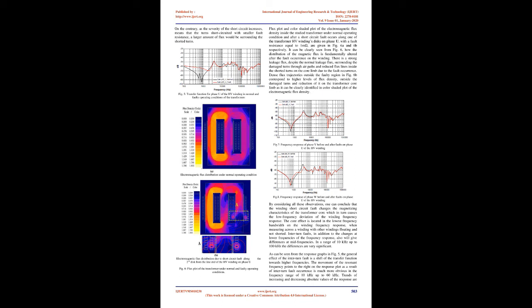Over the course of the experimental tests, a series of experiments were conducted to verify the correctness of the measurement records. Fig 5 depicts two graphs collected in normal and faulty operating conditions of the transformer when the transformer is filled with oil. It is clear from the results that the faulted response is substantially different from the non-faulted response over the low frequency range below 1 kHz.